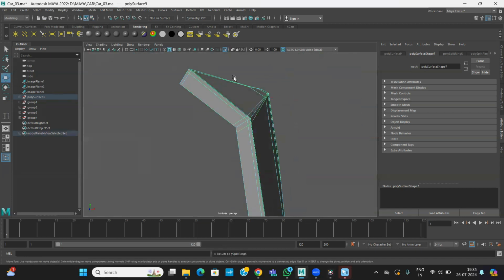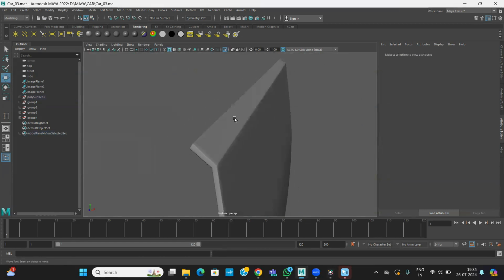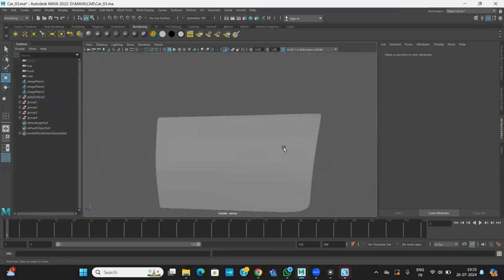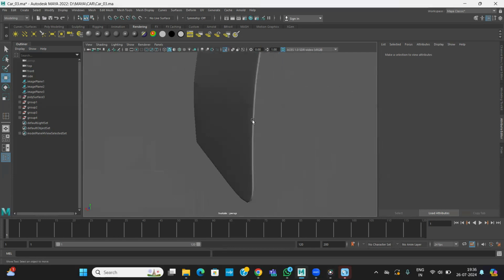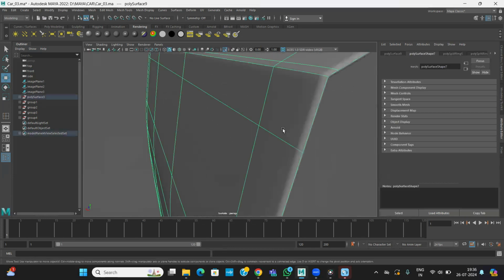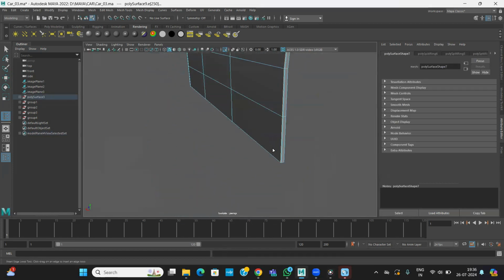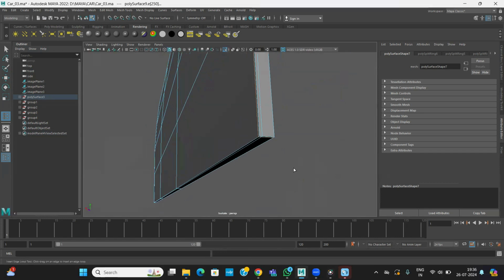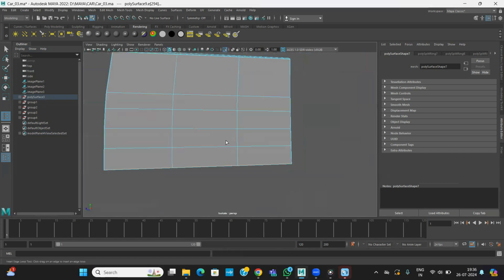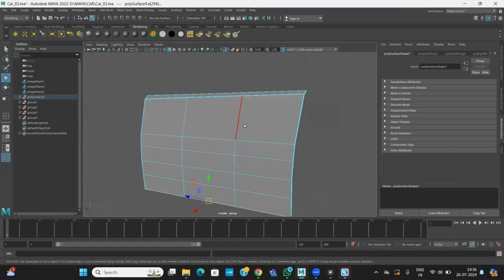Okay, so now stick it up. We'll go for 3. Then you zoom in, that detailing is nice. Looks nice. Looks like metal. So that is the hard surface modeling. And this side looks very soft, because there is no edge loop support. So you can click here and bring it close. So this area got the support. Same thing, you should have the bottom support also that you need. Right. So you can just click and move, and finally this part is over.